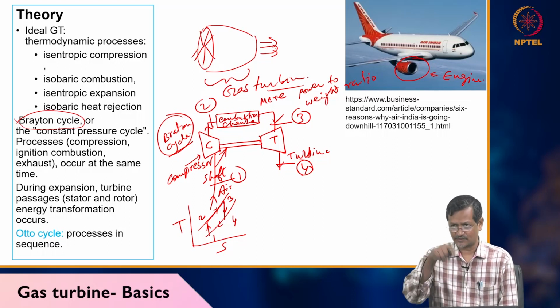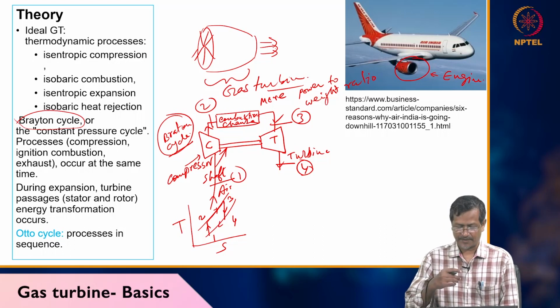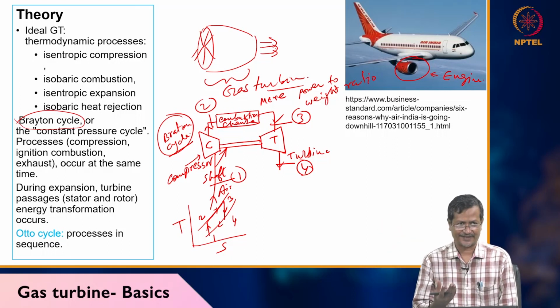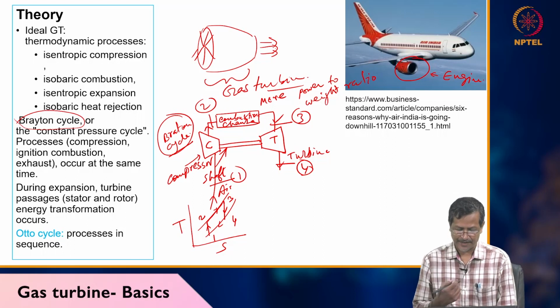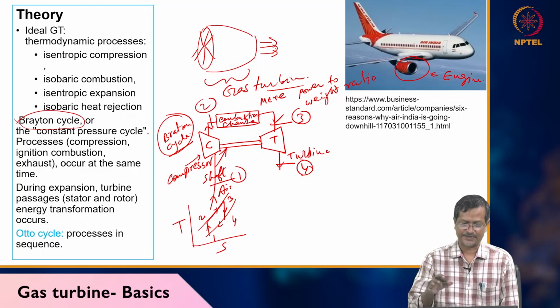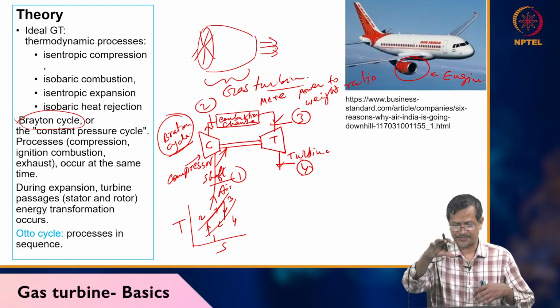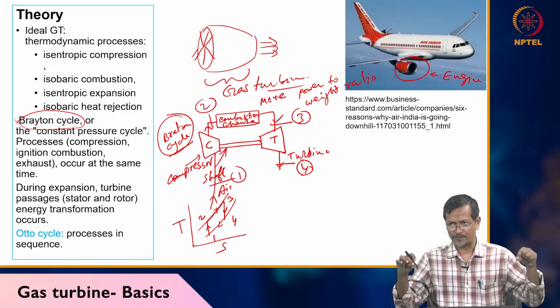many books will put it as one complete cycle. But in an aircraft gas turbine engine, this type of engine, it is not actually a complete cycle. Burning happens, exhaust happens, then the same gas you cannot put in your compressor because oxygen is not there, only flue gases are there. But that high temperature gas can be used for other purposes, which we will discuss later.